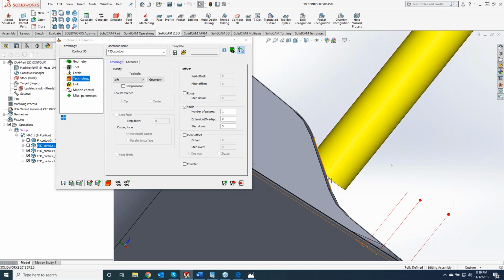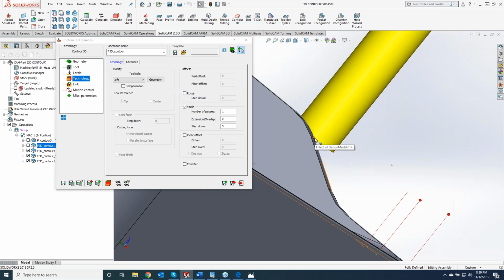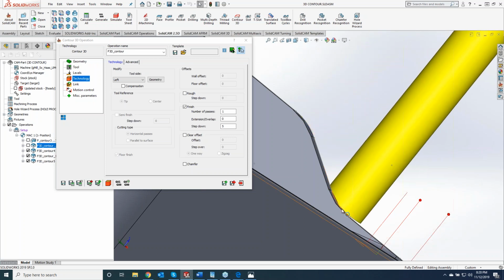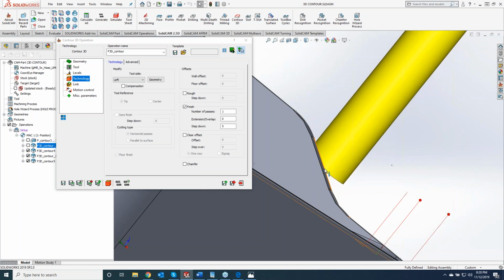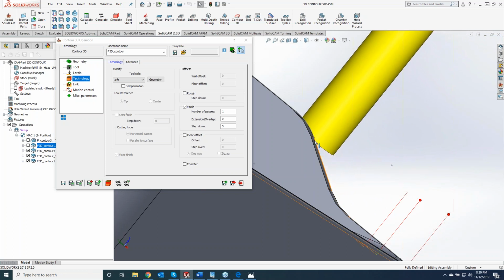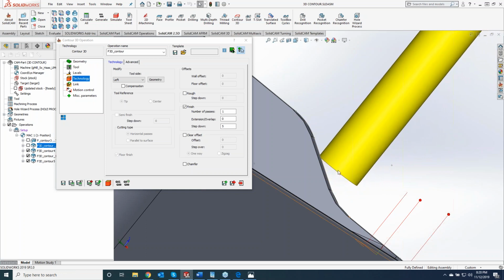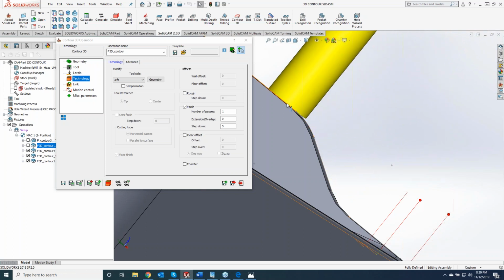And since we're using Contour 3D, it doesn't see it as gouging like HSS or anything like that, because we're telling it that we want to drive it off of the center of that tool and follow that line. So that's what Greg was getting at with gouging into your material. If you were coming up here, you could see that it would be gouging in using the center of that tool, versus on the tip where it would just be working its way around. You can do the same thing if you're looking at the reverse of that as well.